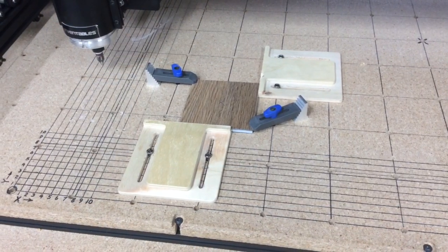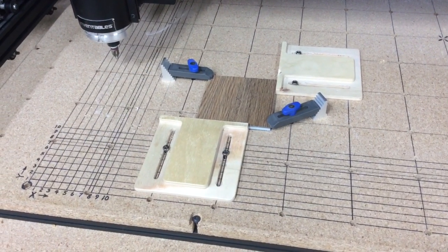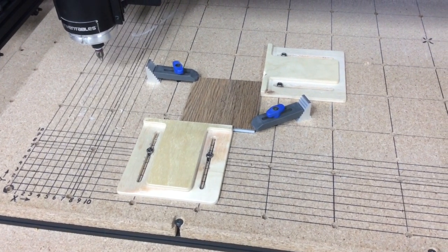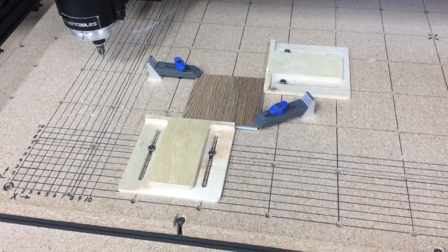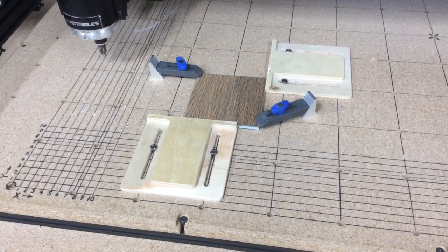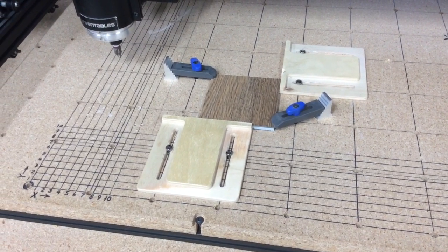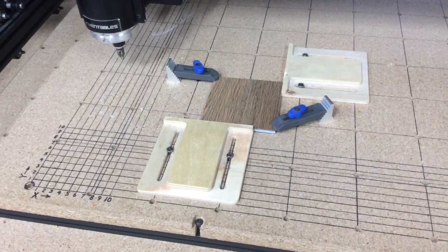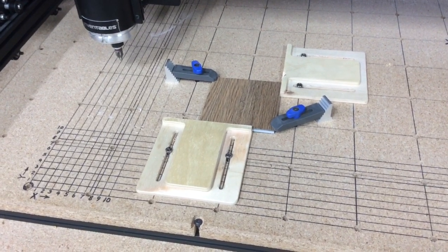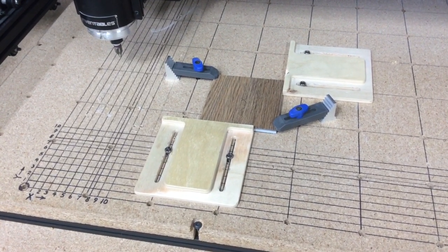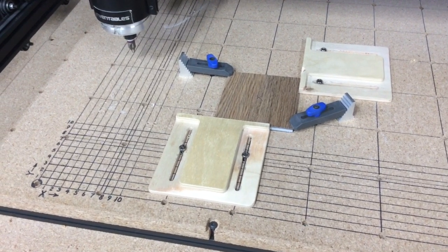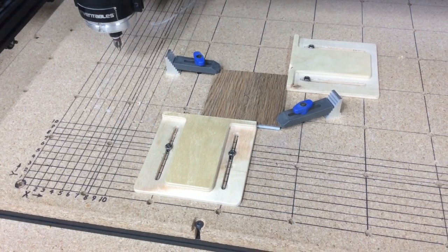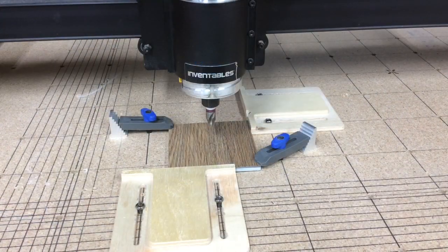Now I went ahead and secured the material on the X-Carve, and I'm using 2 bump stops, and I'm also using 2 of the clamps. The reason I'm doing that is I do want to make this as a production run and make a set of the coasters. And to be able to do that, the bump stops will hold it in place. The clamps will keep it nice and secure when carving. I have the XY axis set for the center of the material.